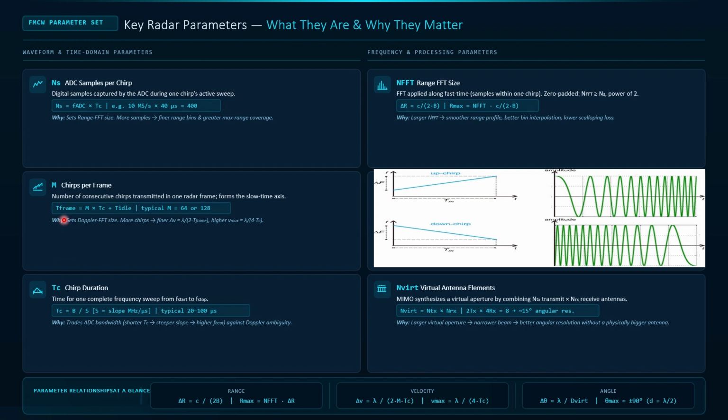that's called the time frame. Okay, and that's going to give you the maximum velocity you're going to get from the radar. And also it's going to give you delta v, so basically the velocity resolution. Okay, so these are the two key things, range and velocity.